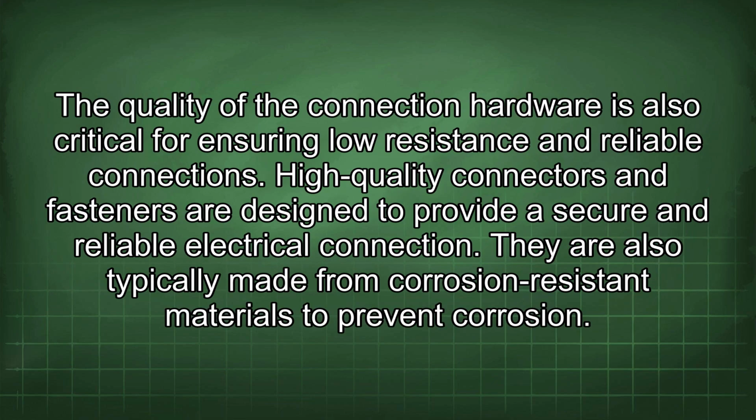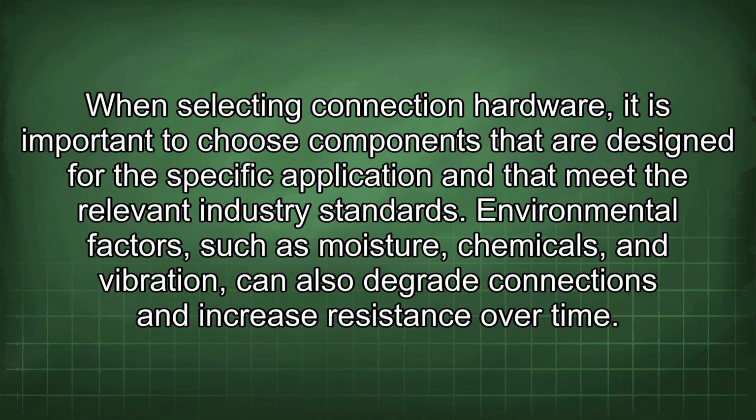The quality of the connection hardware is also critical for ensuring low resistance and reliable connections. High-quality connectors and fasteners are designed to provide a secure and reliable electrical connection. They are also typically made from corrosion-resistant materials to prevent corrosion. When selecting connection hardware, it is important to choose components that are designed for the specific application and that meet